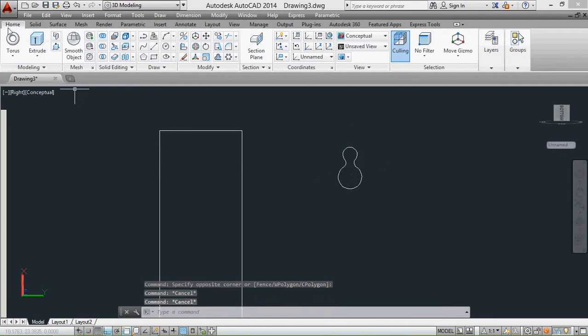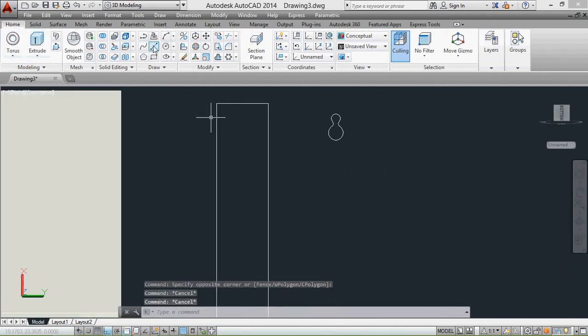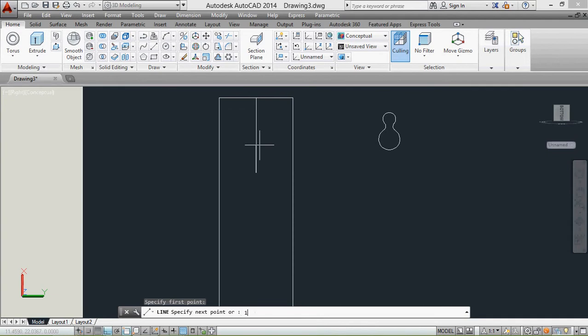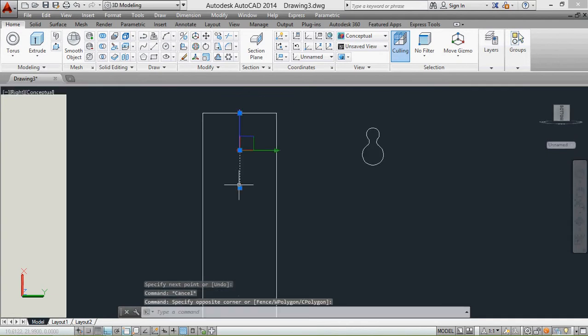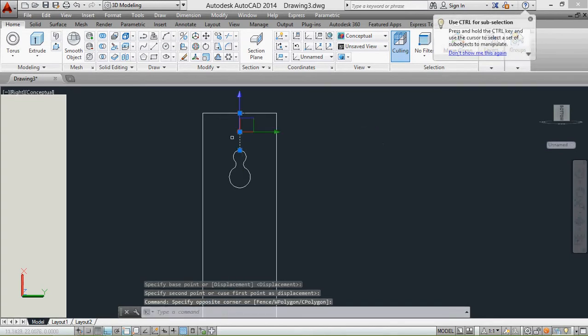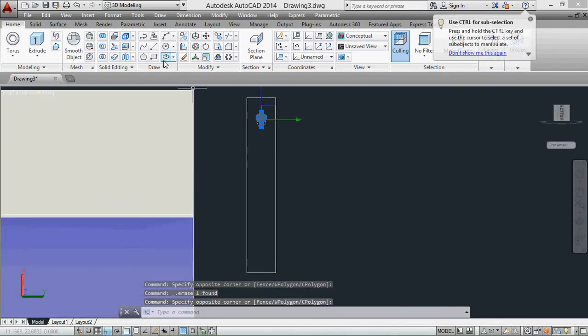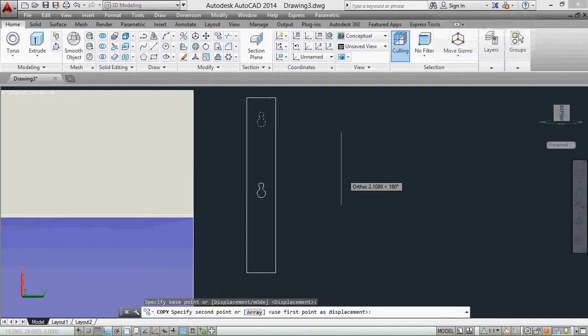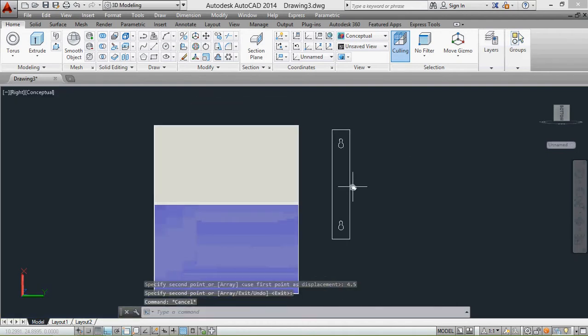What we want to do is center it over that bracket with about a 1-inch gap at the top, or a 1/2 inch, to give it the strength we need. So I'm going to move it over from the center to that, and you can mirror it or copy it over at a distance, about, this one's about 4.5 inches. So you have something like this.